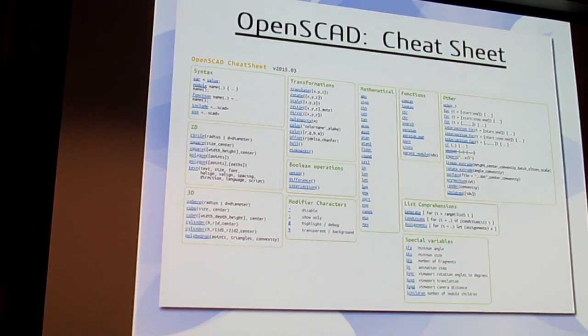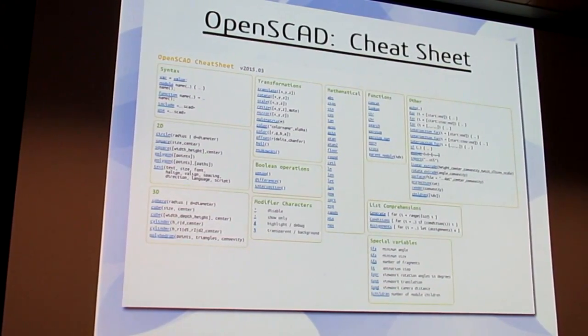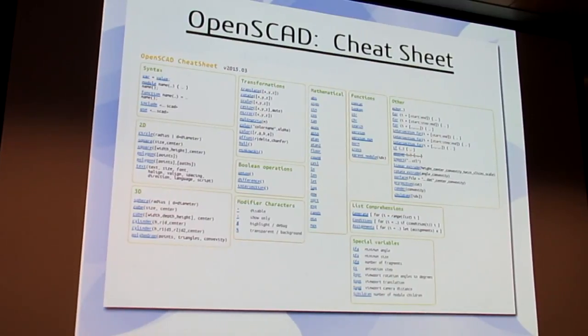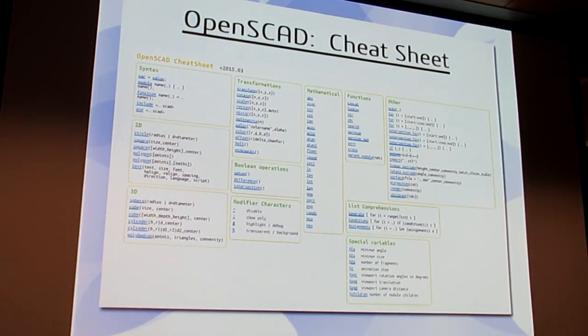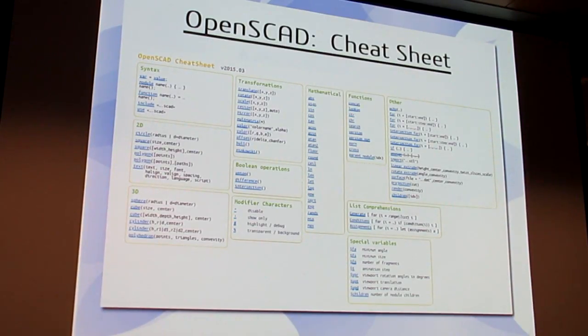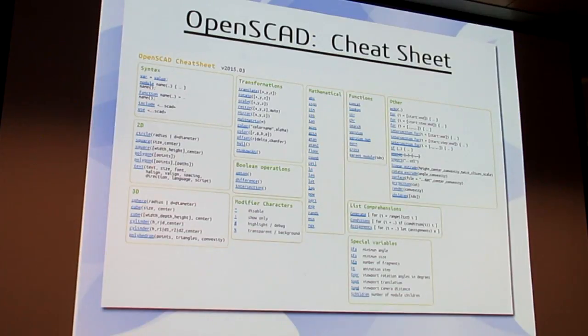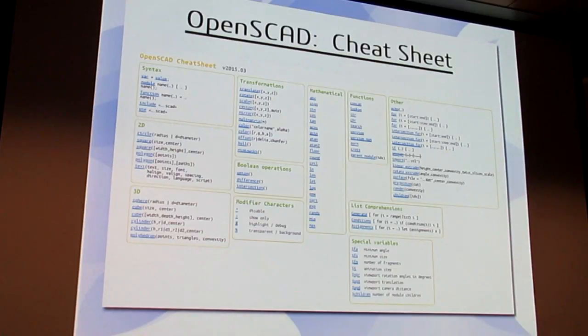Basically you can start with 2D primitives like circles, squares, polygons, mostly in text. A 2D outline you can then extrude, either sweeping it through a curve to create a 3D shape, or just linearly extruding it. The key ones we'll talk about are spheres, cubes, and cylinders. They're the 3D primitives that virtually everything gets built out of. You assemble them together using various transforms, such as translate, to position it in space, rotate it, scale it, etc. You can apply attributes like colors and offsets, some more advanced features, and then you can combine them together by union, difference.